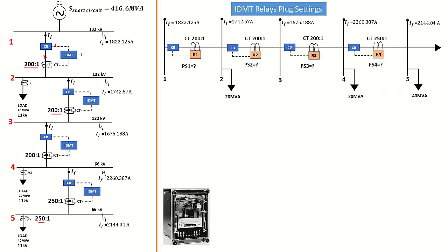The load current that is going to be flowing into the relay, because just like a circuit breaker, there is a normal current that is flowing when the circuit is operating. So that current is the load current. The relay must not trip when that current is passing, because that's a normal condition. The relay must only trip when the current passing through it exceeds the load current.